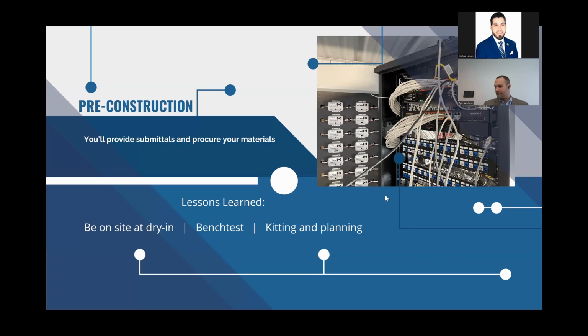Once it's on frame, call me when you're on frame, with no insulation and nothing, so we can protect the wiring. Take a picture up here. There's a video for the room, same as we're doing here. If it's going to be close by, we just try to be away from electrical wires, because sometimes they need to do their work, or we elevate them. According to the code, some cities require it to be higher, away from the electrical.